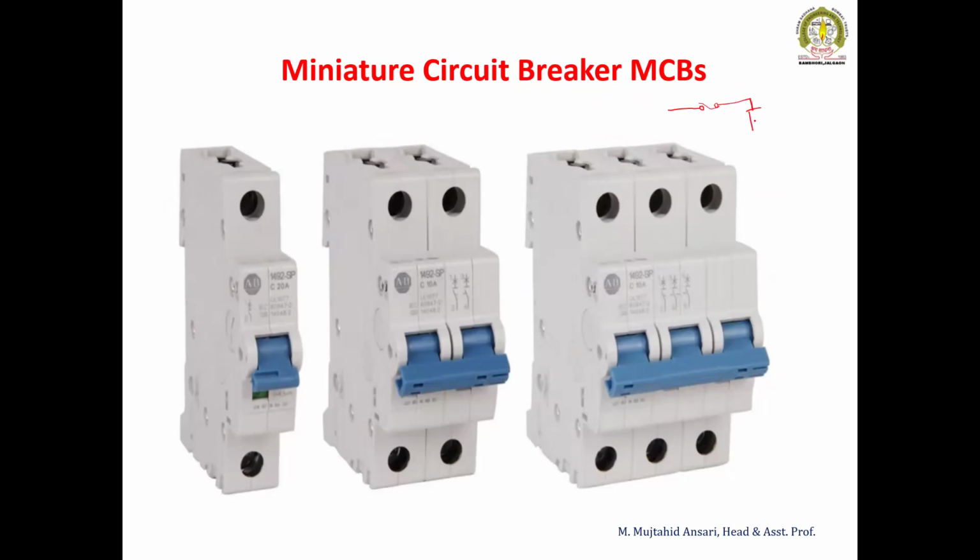Whenever the load increases beyond its capacity, or a fault occurs, like a short circuit between phase and neutral, then this fuse is going to blow out and it will open the circuit. So it will protect the appliances, even human beings.